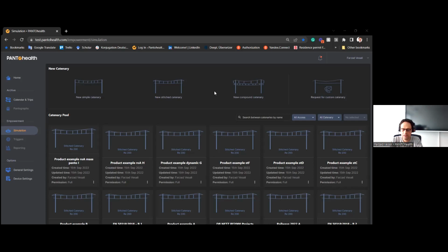Another benefit of this software is modification in, for example, neutral sections or in curves or some points where you have unexpected wear rate in the contact wire. You can check the reason for this wear rate, and you can modify the line by changing the position of the droppers or adjusting the height of the contact wire a bit, and avoid such a high or intensive wear rate in your contact wire.